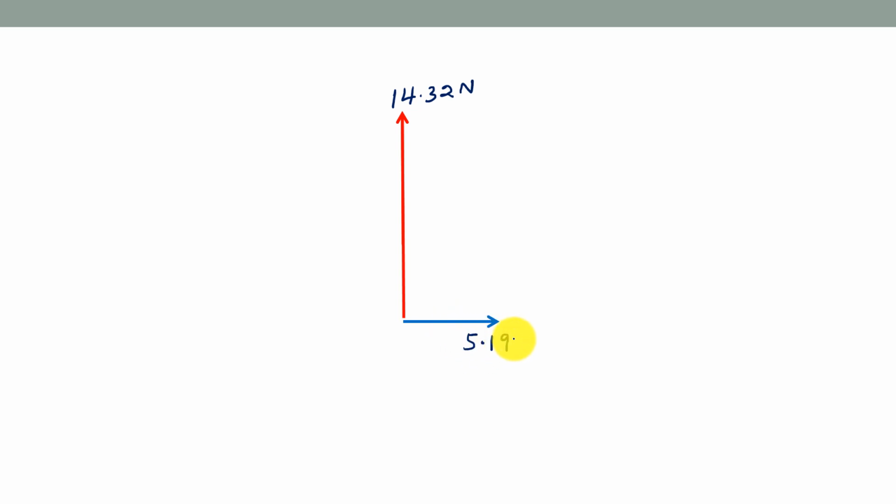As already explained, this force here was 5.196, after the 5 newtons and the 5 newtons cancelled out, leaving the only component which was due to the 6 Newton force. The horizontal component of the 6 Newton force is the one which remained. Now we've got two forces which are exactly perpendicular to each other. You can see this angle is 90 degrees.